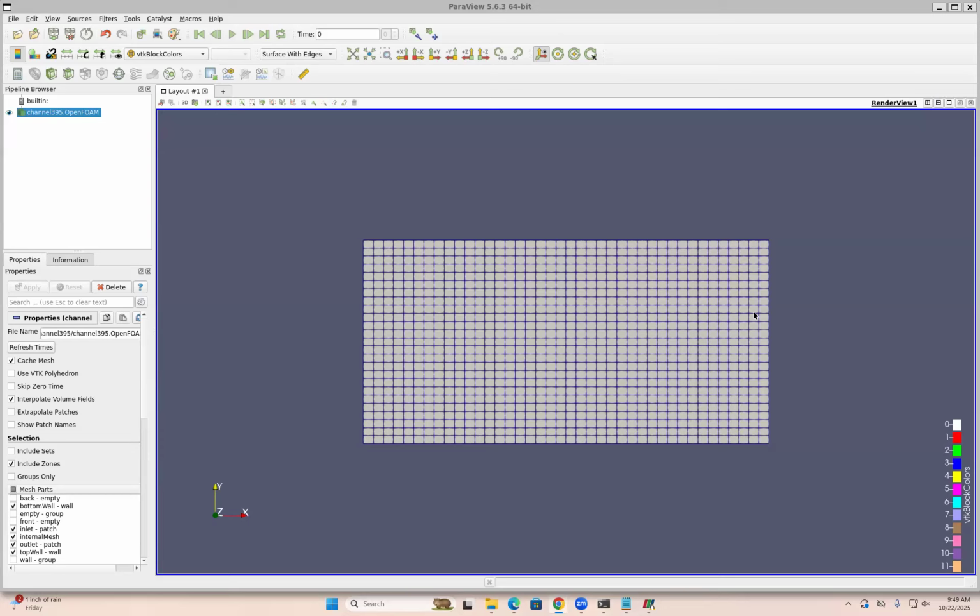Then we will go to turbulence, because I can directly teach you k-epsilon, k-omega properties there itself. If I teach right away, it will be a little bit confusing. The basic part we are going to solve is creating the mesh. The major part in OpenFOAM is creating the blockMesh dict, because the remaining things are the same. U and p values you can give, whichever side the velocity is on. How you define the faces is the most important thing in OpenFOAM.